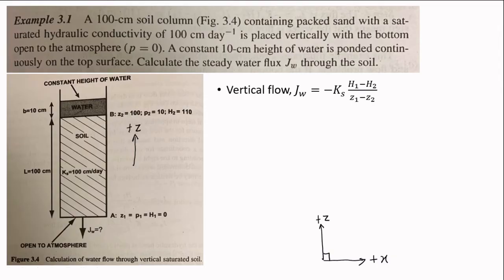If you look here, there is no elevation of water at point 1. So of course p1 will be 0, because no water means no pressure. And z1 is the elevation which we defined as 0. So h1 equals p1 plus z1, which equals 0. That's what it means.